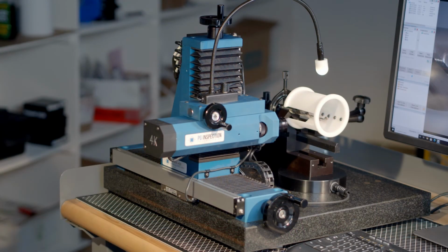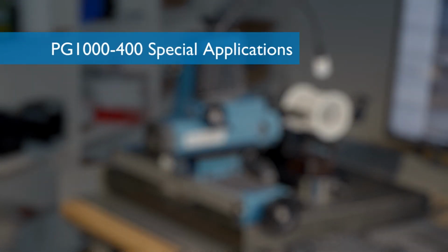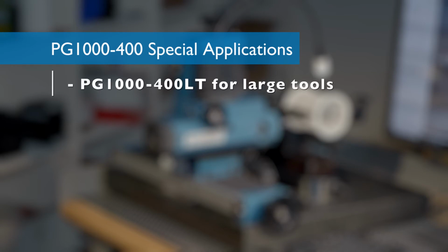In addition to differences in tool size, magnification level, and encoder count, there are a few variations on the PG1000 400 which allow for specialty applications. There's a PG1000 400 LT with a larger granite base and taller column that allows larger tool inspections up to 5 inches in diameter or up to 13.4 inches long. The standard 400 will measure tools up to 3 inches in diameter or up to 7.5 inches long.